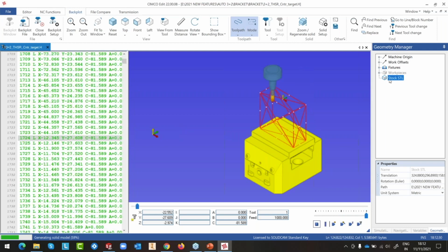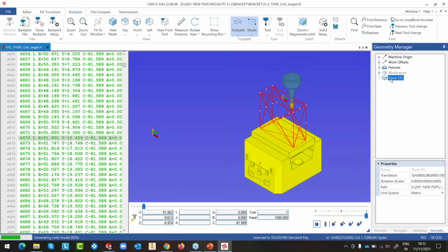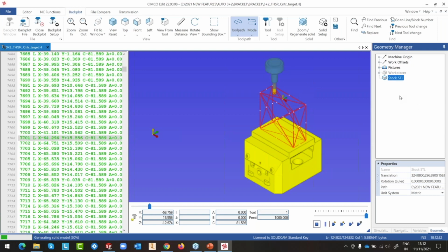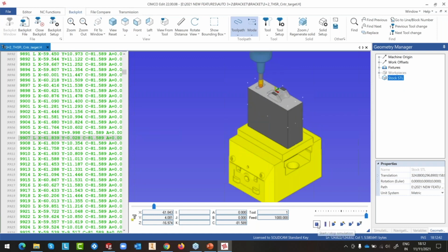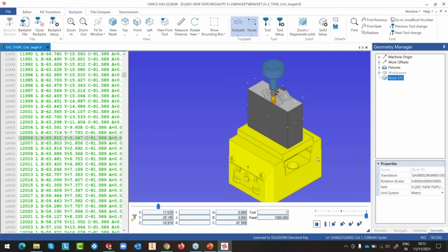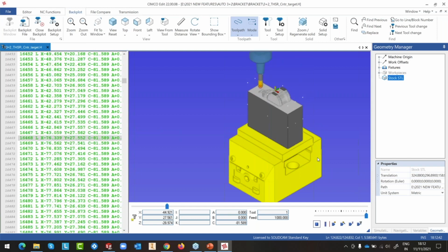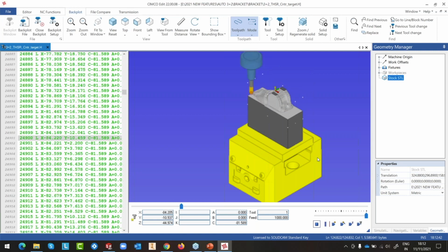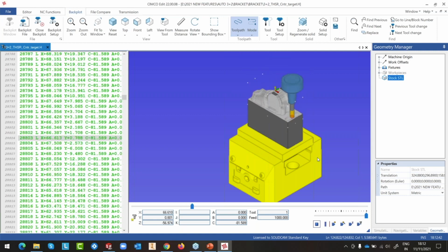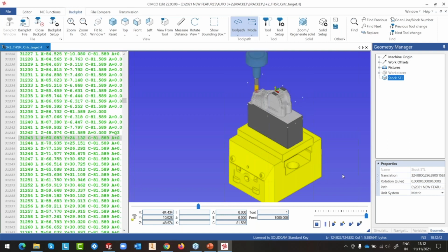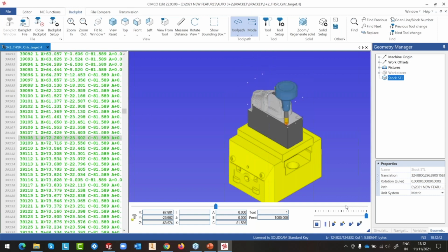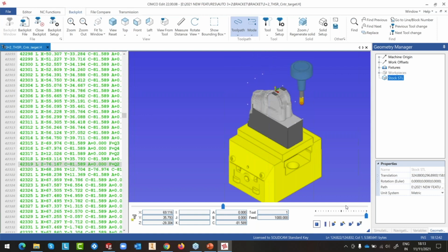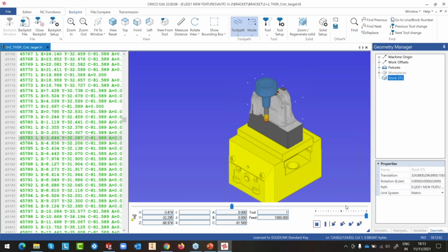Sorry, I didn't see that it was regenerating. So you can see that it not only understands the G62 68.2, but it also understands the tilts and other things from Heidenhain also. So you can run safely and check what is happening exactly on the machine. We'll wait for the simulation to get over, and then we will run some nice looking NC functions on this.